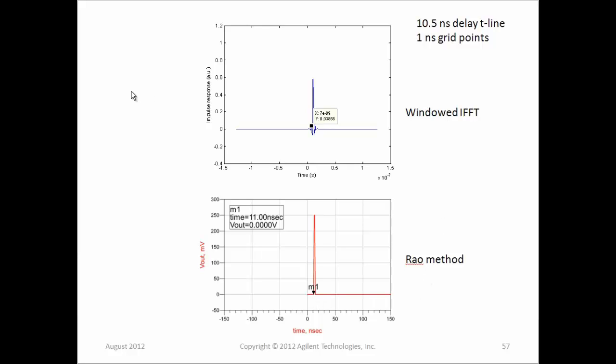So the way the method works is we extrapolate the band-limited parameters in the frequency domain, and we extrapolate the amplitude according to the decay of the amplitude of the given S parameters. We construct a phase relationship from that extrapolated amplitude which satisfies the Kramers-Kronig relationship, using that mathematical relationship between the odd and even parts of the functions.